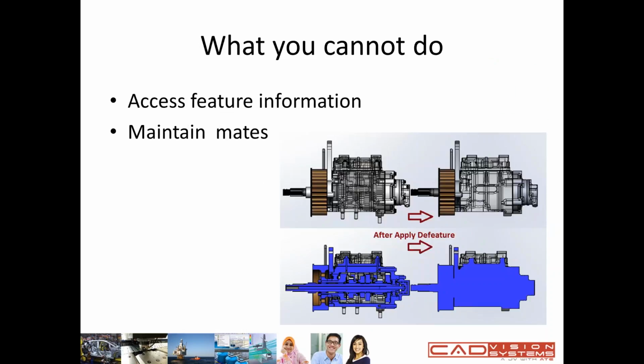And what you cannot do. Once you apply defeature, you cannot access the feature information anymore. You cannot maintain the mates as well. If you see the picture below, in the right bottom corner, the left hand side is before I apply the defeature, and the right hand side is after I apply the defeature.